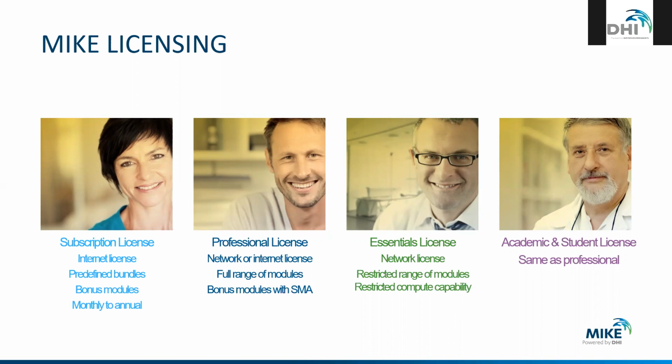You get a number of bonus modules with the subscription, such as the MIKE Animator, which is a results visualizer, and certain compute capabilities of the software are unrestricted in the subscription license. We then have 2 perpetual licenses, which are professional and essentials. And the professional license, basically you can choose exactly which modules you want from the full range of available modules. So you can pick and choose and build your own license. And there's some dependencies, of course, on certain modules. For the advection dispersion, the prerequisite is that you have the hydrodynamics.